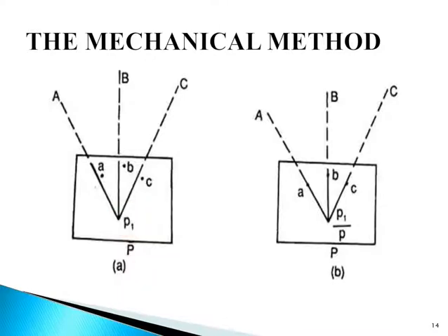With the alidade centered on point P, points A, B and C are bisected and the rays are drawn. So all three rays are drawn. These rays may not pass through the points small a, b, c. As we can see in the image, the rays are not passing through the points a, b and c, as the orientation is done approximately.